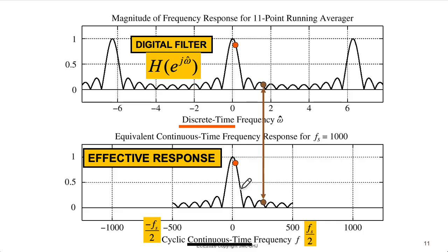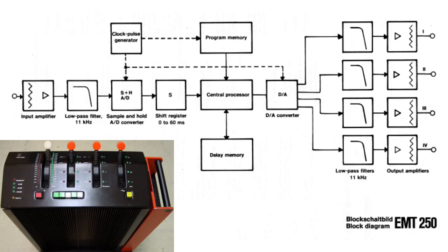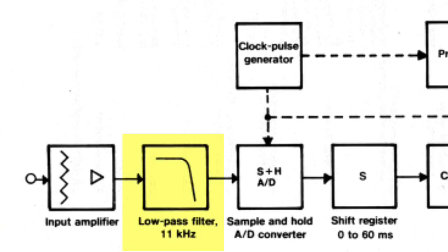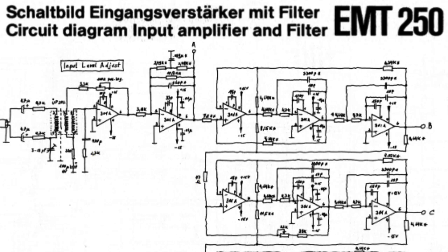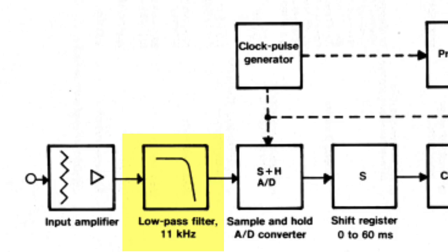So the setup is acting like a continuous time, linear time invariant system, if the input frequencies are less than the Nyquist frequency, which is half the sample rate. If you try to put in a frequency that's bigger than that, then you get aliasing, and you've kind of broken the contract. You'll get new frequencies, and it's not an LTI system anymore. So generally, when you build systems like this, you have some sort of analog filter built with things like operational amplifiers and capacitors and resistors in front to make sure that aliasing isn't a problem.